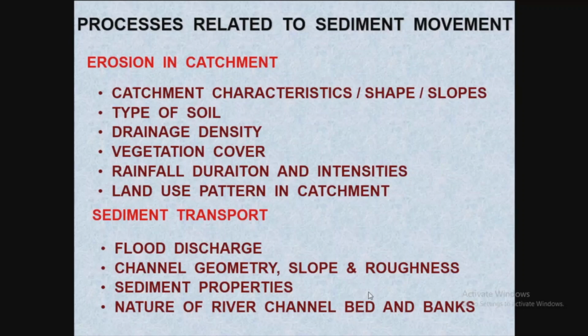Now sediment transport: because of heavy floods, velocities are very high, and because of that velocity, banks and bed are heavily eroded, and channel geometry and channel slope are changed. Channel roughness is changed.